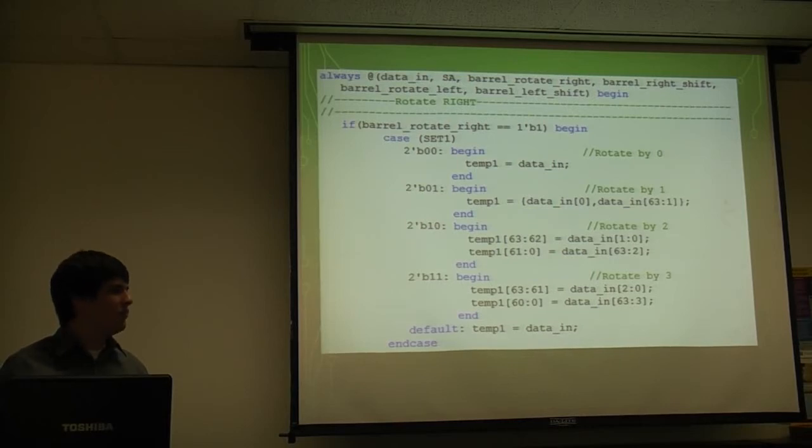No, it's just an unsigned value, so it can be 0 through 63. That was also in order to fit it into the instruction format. We only had 6 bits available, so that's 64 values, and we couldn't really add negatives.